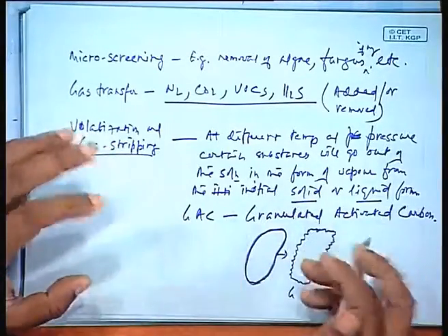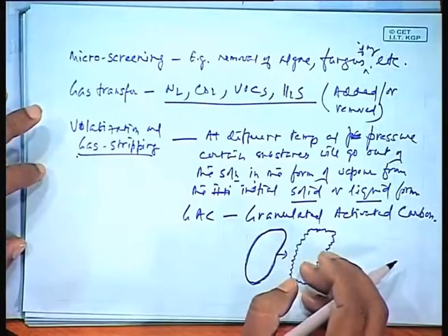Coal has a lesser surface area; for the same mass, coal would have a lesser surface area than charcoal, or for that matter coke. As the surface area increases, a number of gases can be absorbed within it. In the water filtration plants you see in your hostels or anywhere, there is one chamber which is full of granulated activated carbon, basically treated and sized charcoal. As the size decreases, the surface area further increases. The water is generally passed through this charcoal.